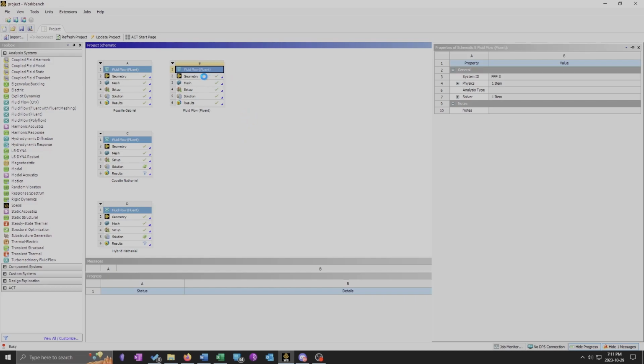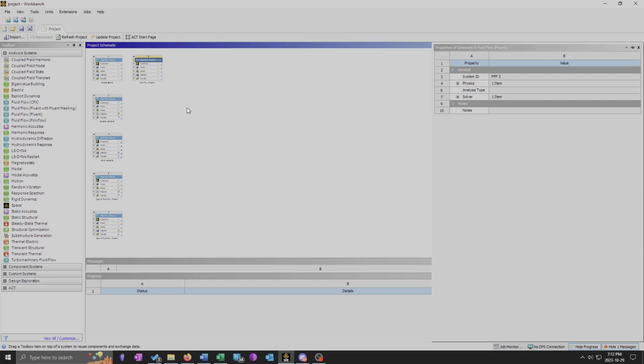And so the mesh is already done, and we have also gotten a format for the solution. So all you would need to do is change the setup and run the simulation again in Fluent, and then you should get the new results. So what we did in the results is we created the line, the chart, the contours, the vectors. The only thing we would have to repeat in that part is exporting to a CSV and finding the max velocity and the location of the max velocity.